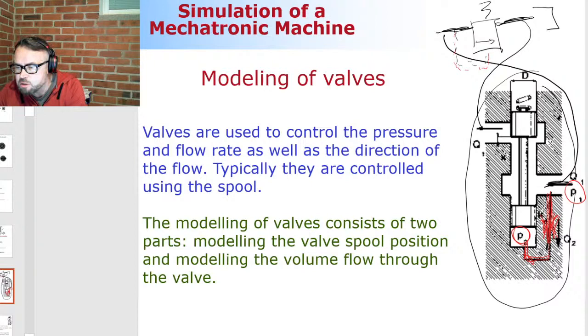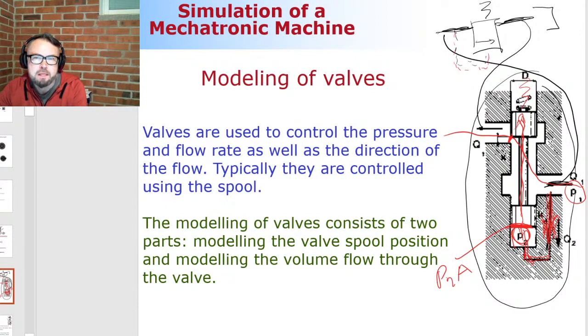Anyway, so this pressure P2 is imposed to this side, and because the pressure is started to push this piston towards the spring. And there is a pre-tension in the spring, and as soon as the force, which is here P2 multiplied by corresponding cross-section area, is become to be higher than the pre-tension of the spring, this spool is started to move upright position. That is opening. And what happens in that case is that there is a kind of like a area where the flow started to travel through the valve. That would happen.